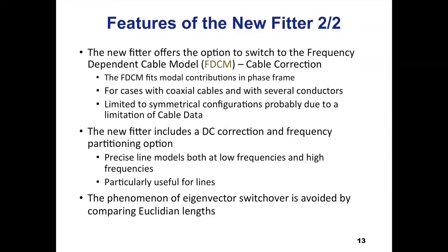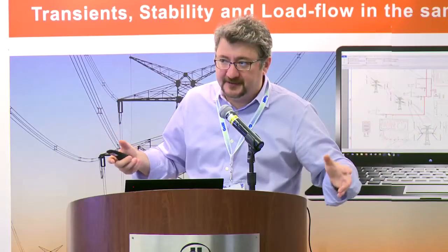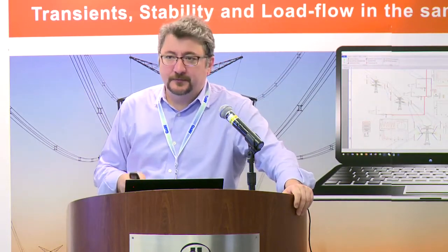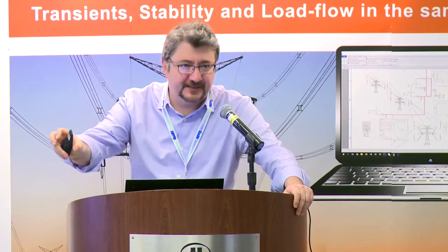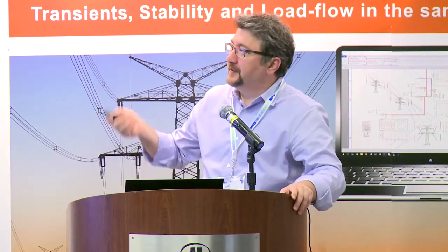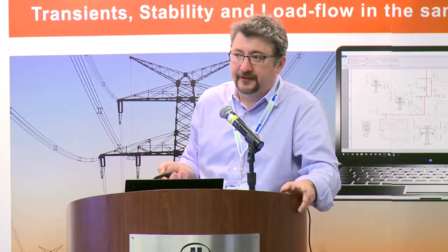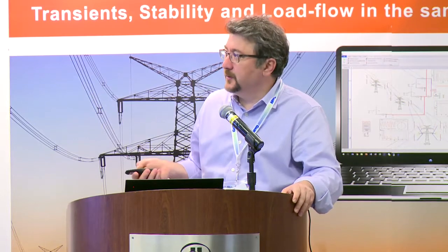And this becomes an overdetermined, so rank-deficient system, so you don't get good results. But with the frequency-dependent cable model, we don't have that problem. We fit each model contribution separately. So this works for 50 cables, 100 cables. There is no such tool right now, professional tool or commercial tool available except this one. So it is a nice feature to have.